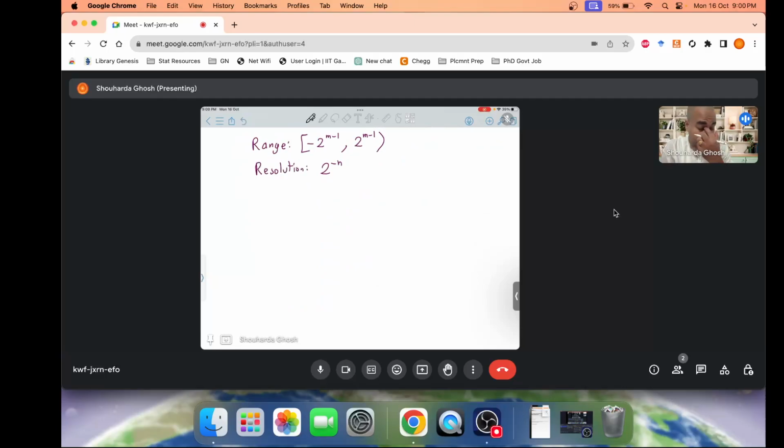So now in the exam you can be given a 4-bit value in general Q1.3, and you are given this number 1011. How do you find the value? They won't give any decimal sign, so it's Q1.3. So you need to understand there will be one integer plus sign bit. So this will be your decimal point, with one bit over here and the rest 3 bits over here.